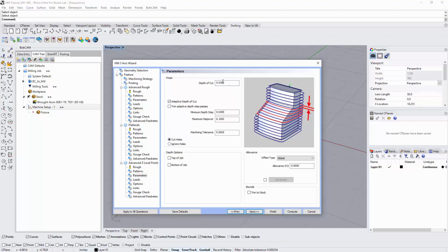So we're going to rough the entire part at 30 thousandths, but in the areas that need more work, I'm going to tell it it's allowed to go down to 15 thousandths. And then in the areas where even if it can't get to that 15 thousandths, it still has to output another toolpath, we could define it based on a step over. So how far does it travel before it steps over again and lays down a toolpath? I'll say 30 thousandths on that. So just 0.03. Again, my machining tolerance, I'm going to leave it at 1/2 thou.